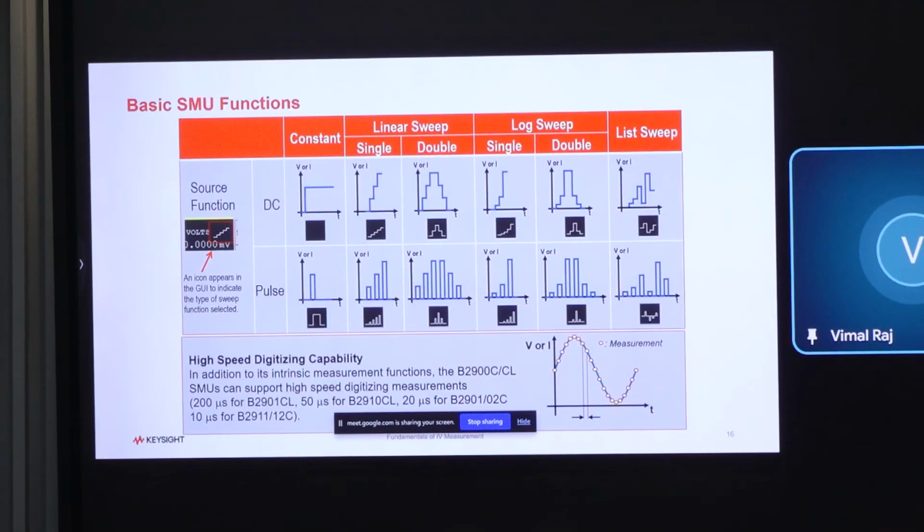Logarithmic sweep means it will be based on 10x steps, then the plot will be switched, and you can see the characteristics. That will be mostly used in the RF measurement, RF sample section. When you are discussing general devices, mostly you are using the linear. When you come to the RF component, they are using the logarithmic sweep.